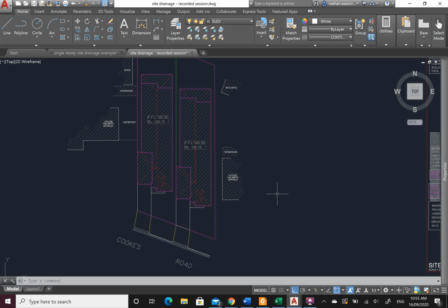What we try not to do is have any water falling close enough that it can come under our foundations and make the clay particles shrink or swell and crack the house. So that's why we have a concrete perimeter around it. It's part of the National Construction Code. We can get away with 900. So if you measure your boundaries, these ones here are 900 as opposed to a meter, and that's okay.